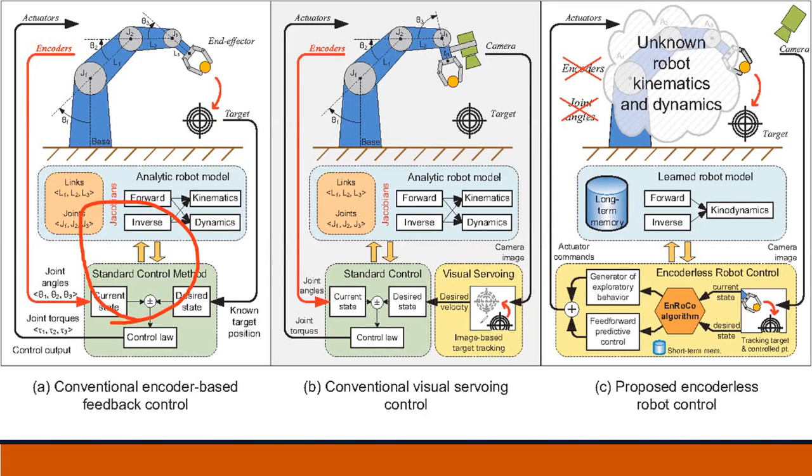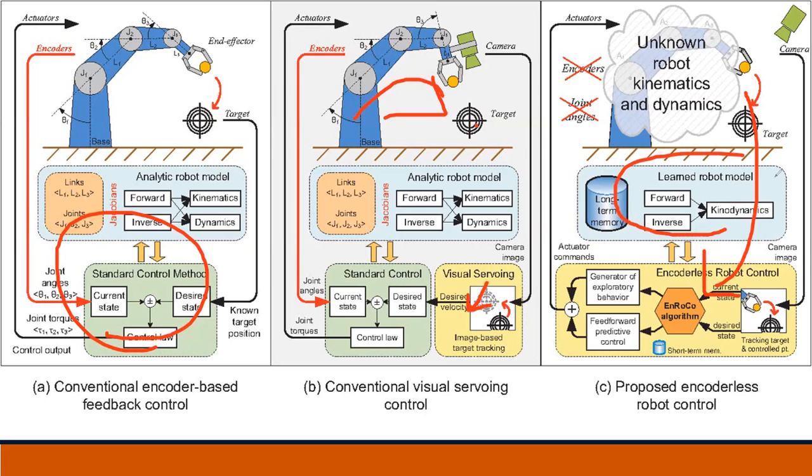The second one is visual servo control. The first one, you just use XYZ to control your robot, a standard control method. The servo means that you do have some feedback, and using an algorithm on the feedback, you then control your robot. The last one is that you have the feedback and you work on the learning model. This one has AI involved, and based on historical data, you control your robot arm. So these are the 3 different generations of the architecture.